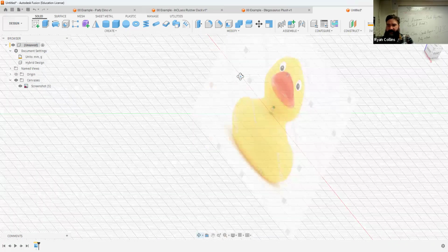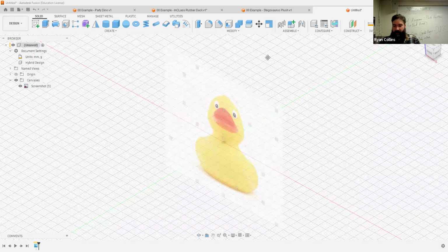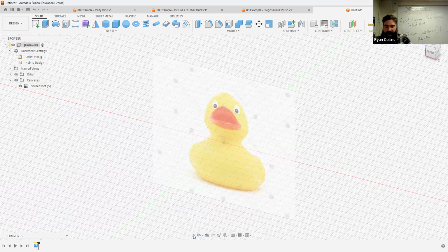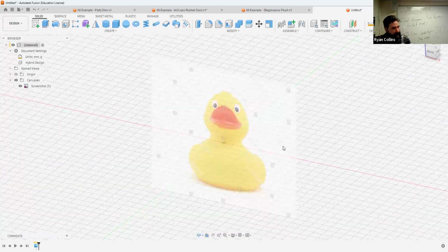Why is this tumbling like this now? One moment. That's because you changed, you're on Calibrate design. The design's supposed to be there. There we go. Yeah. Okay, so we fixed that. What I didn't realize is somehow the orbit options got changed, so that's why it was tumbling as I orbited rather than just moving around. If you go down to the center of the screen, your options down here, where it says now constrained orbit, click the little arrow and it'll give you the options. Somehow mine had changed over to free orbit. So constrained orbit is the one you want. That keeps it from tumbling all over and maintains up, down, that sort of orientation. Okay, cool. We actually have that.